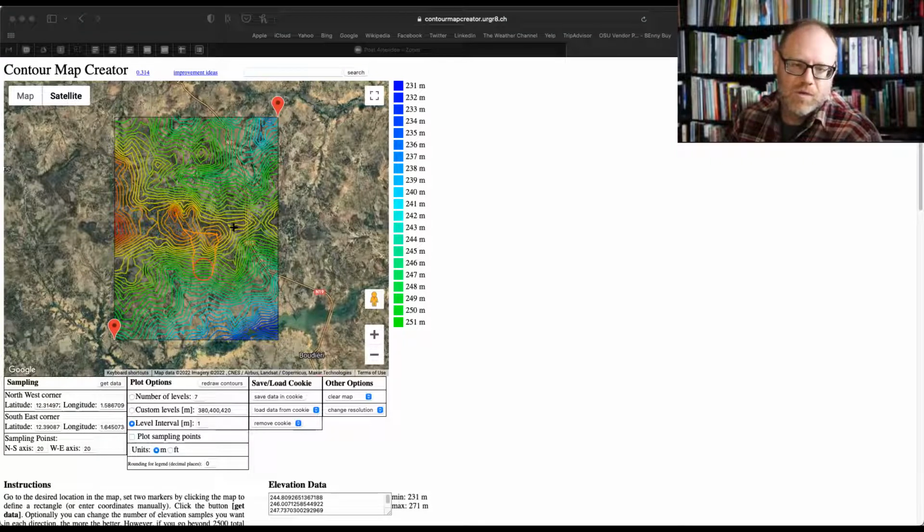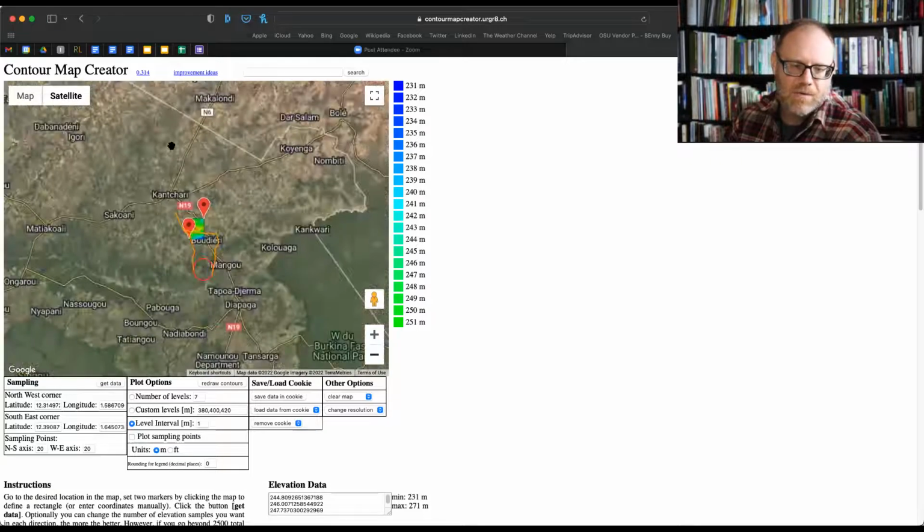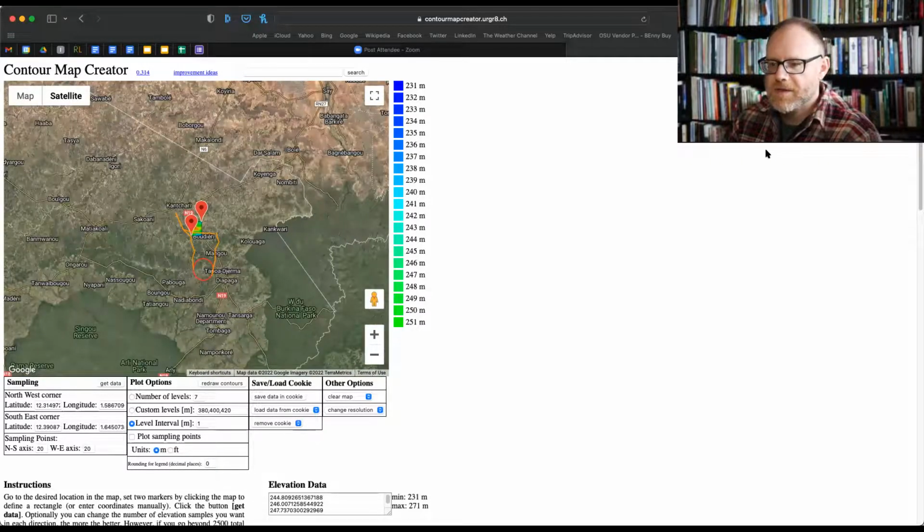And then if you pulled way out, you would get a sense of the macro watershed. What is this area looking like? And so I'm going to clear this, and then we'll have to change from 1 meter intervals probably to 5.